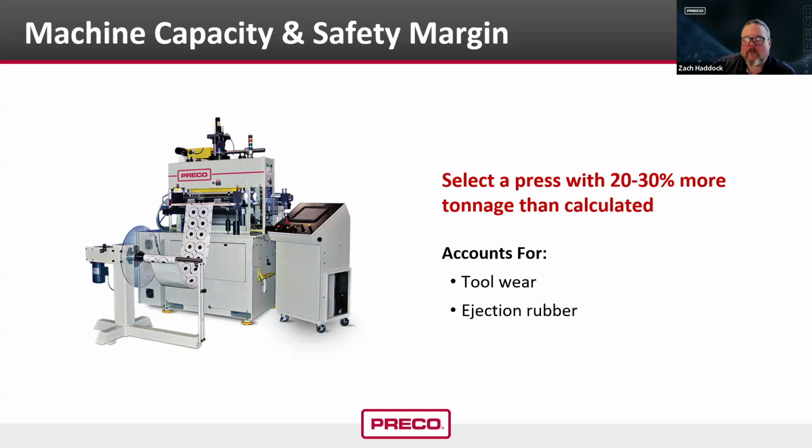The reason that we don't want to run at maximum tonnage, or max out our available tonnage, I should say, is because we could end up with parts that every now and then are partially cut, or they may stop cutting altogether as the die wears. So we really want to make sure that we've always got a little bit of a safety net there, a little bit of a safety margin.